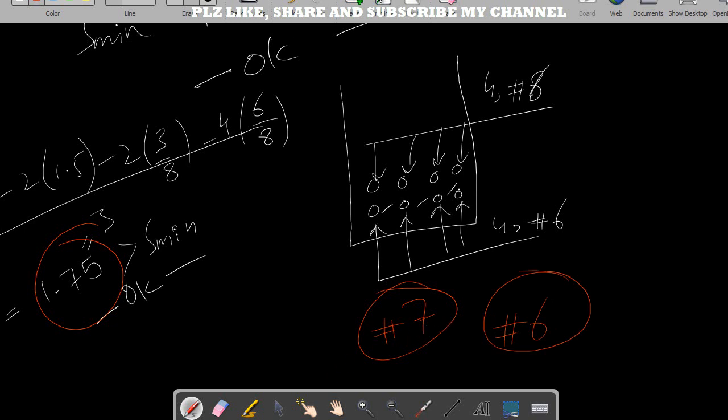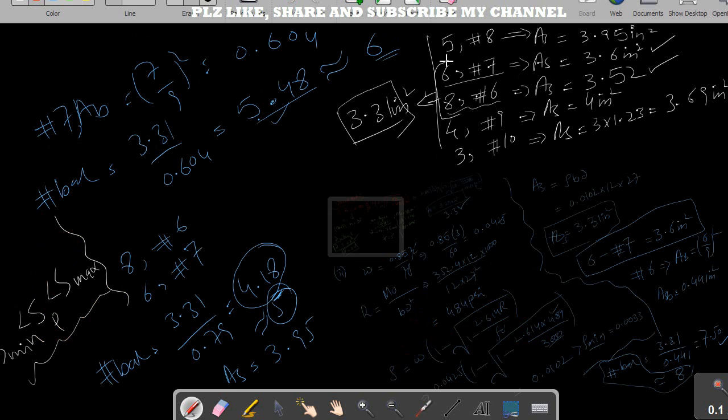So this is the selection. We have to find different arrangements, combining number 6, number 7, number 5 bars, but make sure the design and the arrangement will be simple, and the bars are available. The placing of the bar will be simple, because if we choose different combinations of bars, it is difficult on the site to provide and cast those bars.